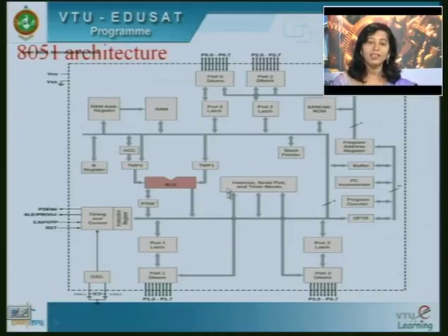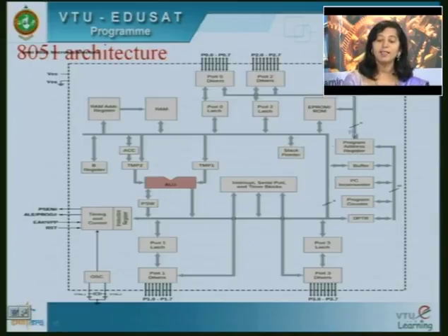And then we have the interrupt, serial port and timer blocks here. As I told you, to prioritize the response, you can use the interrupt block, timer to add delays, serial port for serial communication, and you have a stack pointer here. I will tell you what is the use of the stack pointer. Then program address register, this EPROM or ROM stores our program. So the address for where this program is stored is there in this program address register.